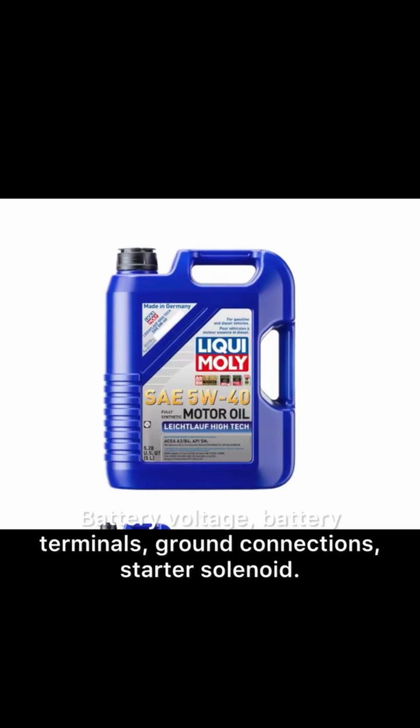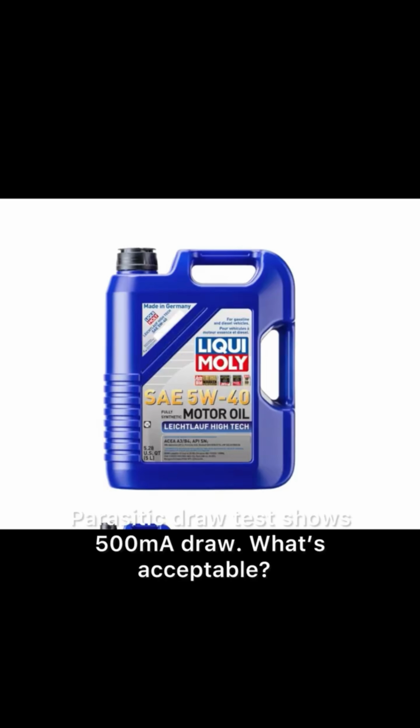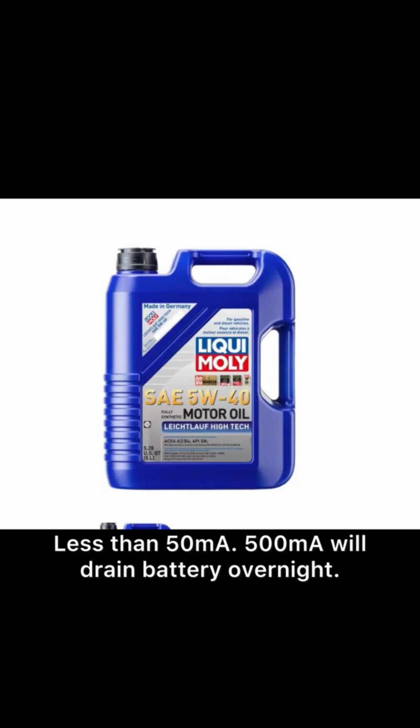Alternator output is 12.8 V with engine running. Is that okay? No. Should be 13.8-14.4 V. Likely faulty alternator or regulator. Parasitic draw test shows 500 milliamperes draw. What's acceptable? Less than 50 milliamperes. 500 milliamperes will drain battery overnight.